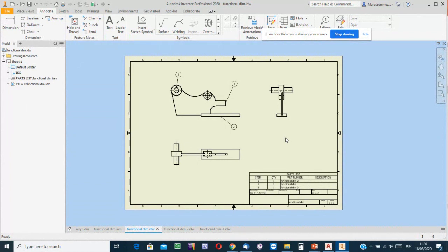If, when we fit the door into the door opening or window opening, there is a very great empty space between them, then using a bulk of cement, concrete, or just injecting some foam or special chemicals can easily fill in the space.